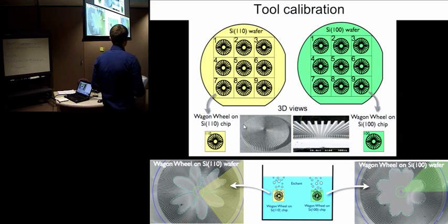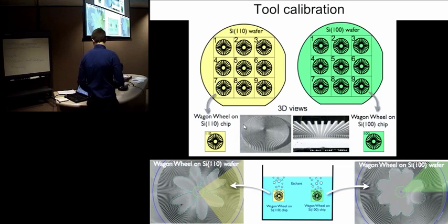And this extracts the etch rates and allows us to calibrate Intella Etch for their particular etchant. If they're working with a different etchant, different temperature, concentration, whatever, from there we can calibrate the tool more effectively. This is something that the users can do on their own, but it's something that our support team does all the time, so we don't mind doing it for them once we get the SEM images from their fabricated sample.